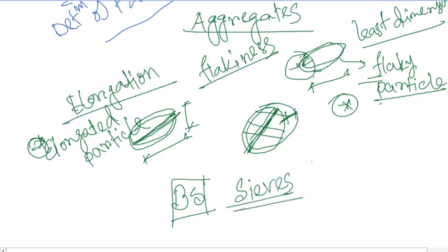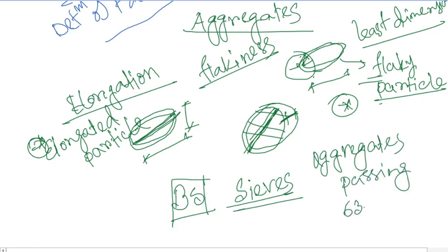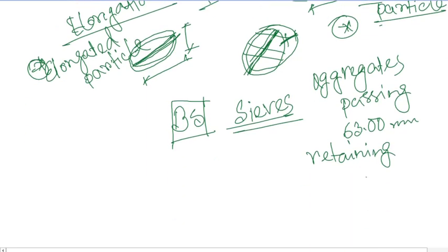For this experiment we will be restricted to the aggregates passing through the 63 millimeter sieve and retaining on the 6.3 millimeter sieve.